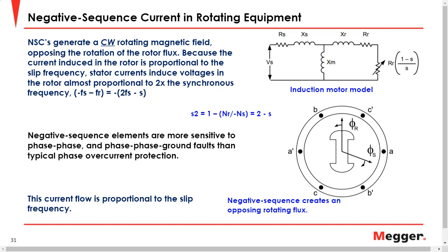Technically, it shouldn't. However, in the real world, even if your source voltage is balanced, the line can still present some asymmetrical characteristics. So your three phases may have slightly different impedances, and that's going to account for some small, often negligible, negative sequence currents and voltages during a balanced three-phase fault.